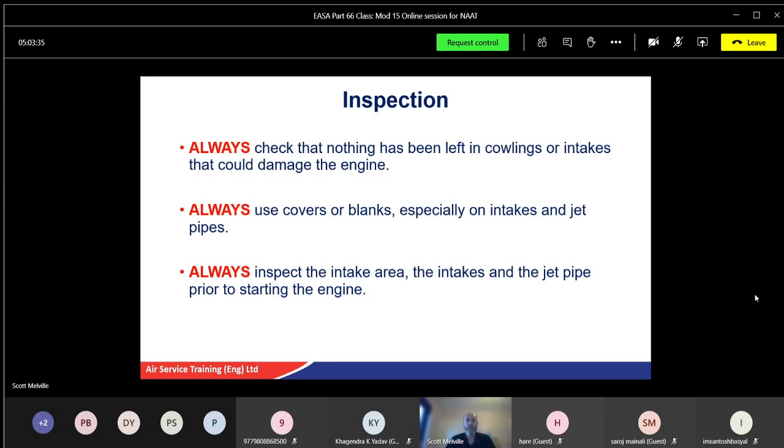So again, water ingestion as well. Depending on the type of aircraft, it's more of a concern for aircraft with long intakes, and multi-engine aircraft. But certainly water can damage a blade, and we call that soft FOD damage. If water is in a pool on the bottom of the intake, once the engine starts it sucks the water in very quickly and will actually bend the blade. That's recognisable by the tip of the blade bending forward, where the water has got behind it, gets spread out very quickly, and acts like a wall and bends the blade forward. And it doesn't take much water to do that.